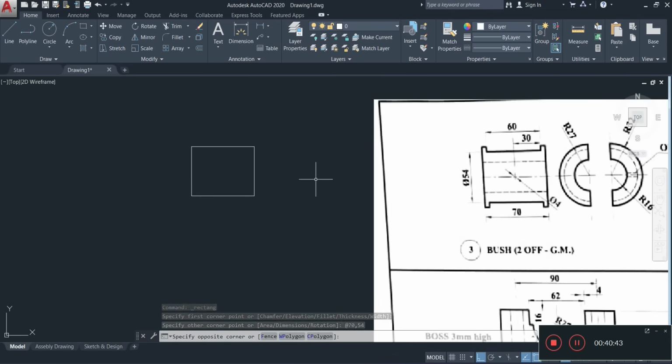Once I've done so, we need to capture this inner portion here. Let's see. What is the 60 representing? Oh, the 60 is actually representing from here to here, but they also have this here as well, which is 30. Anyways, I'm not going to worry about that. So let's just have a relative reference line here in the middle. This might be a bit overkill, and let's offset 30 on either side of that line there. So offset 30, and let's offset on either side here like this.